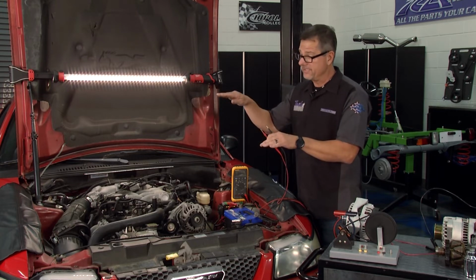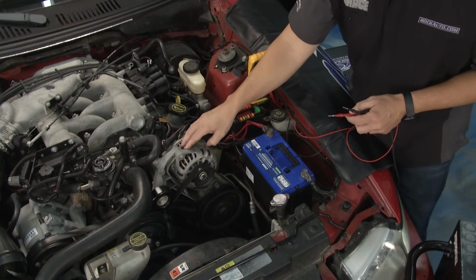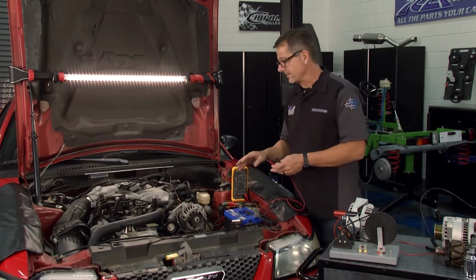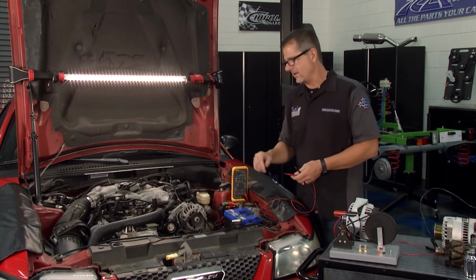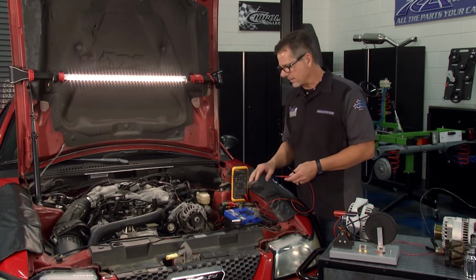But if I put 14 pounds here and 12, it would go towards the battery. So that's what we're trying to do. We're trying to see if the battery will raise up. Now, in no way, shape, or form does this mean your alternator is performing perfectly. There's all kinds of alternator diode tests, and we can do a couple voltage drop tests as well. But we're going to look at that.